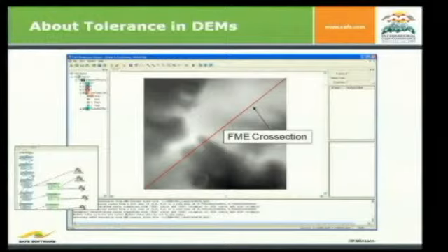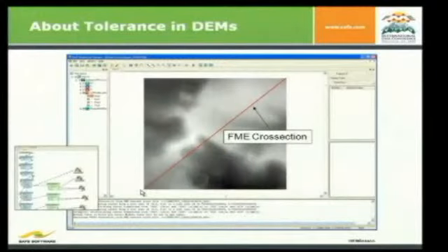As I told you before, we have specialists that can relate to the different tolerances when you generate a digital elevation model. But I wanted to figure out on my own what it means if I use a 2-meter resolution elevation model, or 1 meter, or 10 centimeters. So I made a little tool that automatically reads the laser data files and creates the digital elevation model. It's a little custom transformer, and you can set different interpolation algorithms in it.